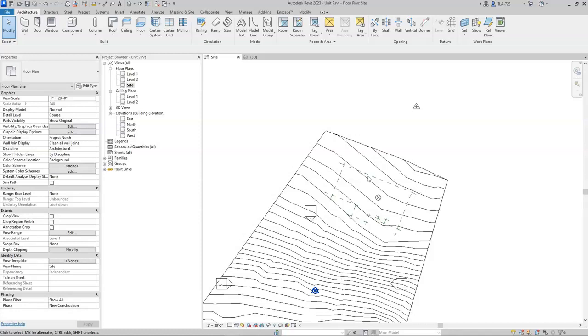If we set that house right where it needs to go, so that for example your driveway is sloping correctly, and you're correctly positioned above the sewer that's running under the street out front, all of these things require a little bit of research and evaluating the best way to do this. And of course, if you're going to have a walkout basement, how can we place that basement floor within the ground so that a minimal amount of dirt work needs to be done and you don't have a bunch of water flowing into your basement when it rains?